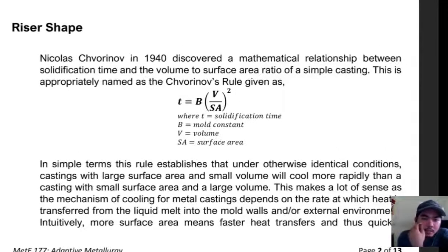So this is just the module natin. So again, by Chvorinov's rule, yung time ng solidification is directly proportional dun sa volume to surface area ratio. So again, itong volume to surface area ratio is a very important concept kasi dito halos lahat nag-base yung calculations natin when it comes to riser design.